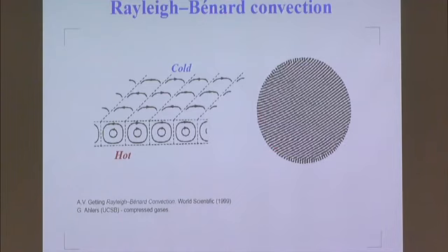So the dark regions are fluid that is rising up, and the white regions are fluid that's falling down. Those turnovers are, in cross-section, eddies in alternate directions, and the flow is driven in Rayleigh-Bénard convection by having uniform temperatures applied to the lower plate and the upper plate.